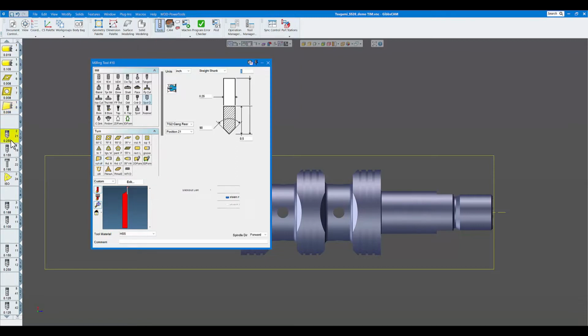In the next section here, I have gang rear side, and here I have my drills, my tap, and threading tool. Next section, I have gang rear drilling for these two. Next section, I have gang front drilling. Next section, I have gang basic back drilling there. Next section, rear side back tools, and the last section is going to be back tool post. So I have all those lined up.